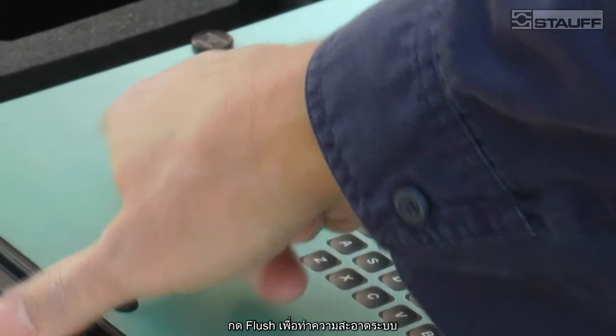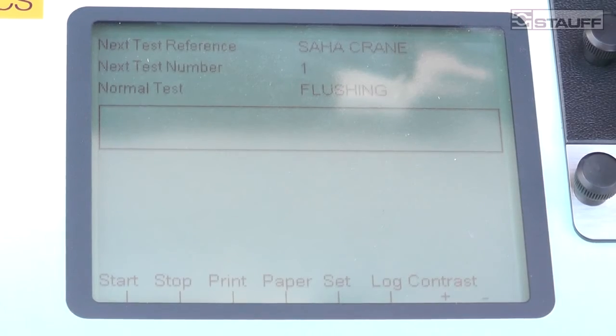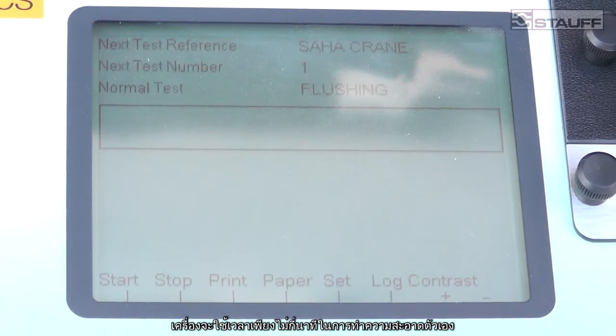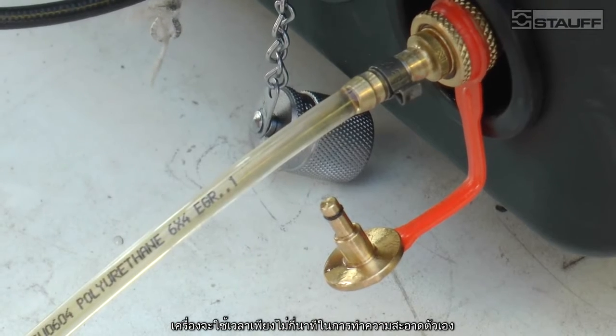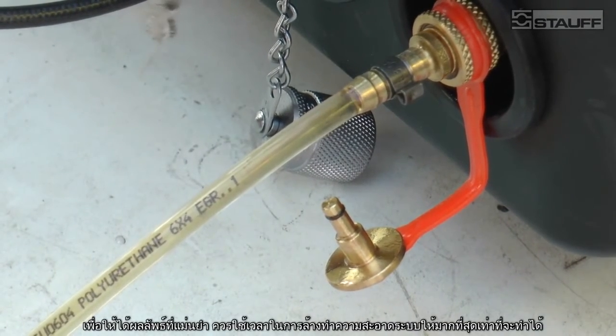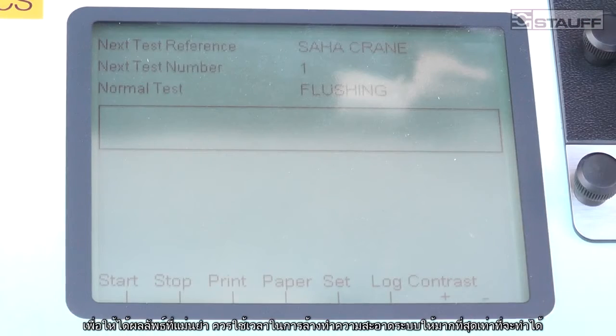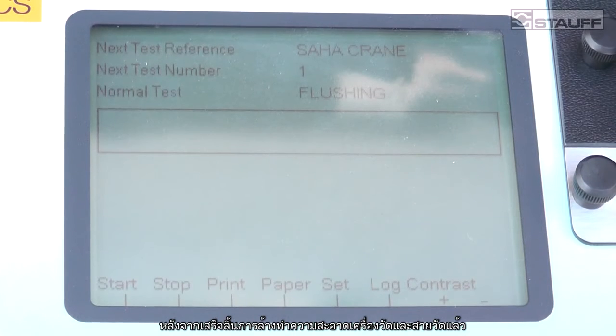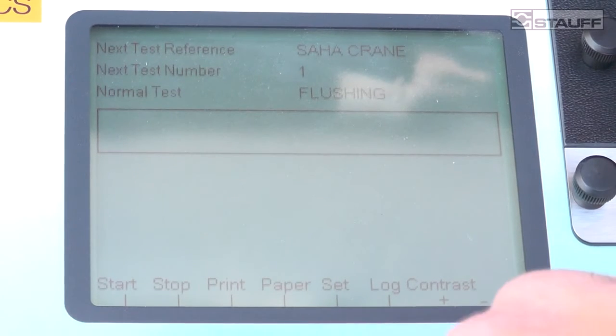Press the flash button and start flashing for a couple of minutes or seconds until you've had enough time to flash the particle counter and the hose. This is a bit longer hose than in the previous test, so make sure you give it a good flash. And now we're ready to take the test.